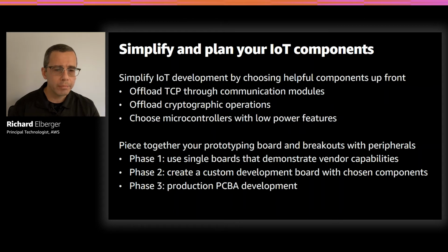And then, when you're prototyping, you are directly connecting the board to your laptop, right? And you're getting direct power, so you may not think about this, but running on battery has other considerations, and having the low power capability isn't always enough. Ensure you're looking at the SDKs that the silicon vendor provides for your microcontrollers to help you out with that. For the seasoned IoT folks out there, you know that once you've done a sanity check that the components work well together, the hardware guys will start designing the PCBA for the development effort, all right?